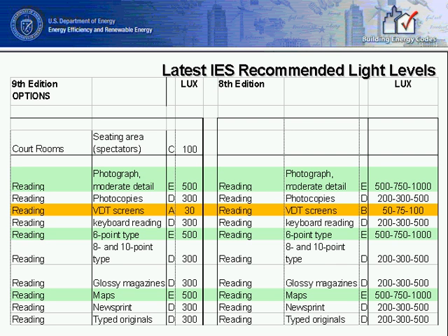The basis, again, one of the basic inputs, is recommended light levels, and here you're looking at the recommended light level values from IESNA. There's a 9th edition and 8th edition represented here, and what you're looking at, of course, are all of the different reading values. And these form the basis of the models, which we'll look at in a little bit more detail.